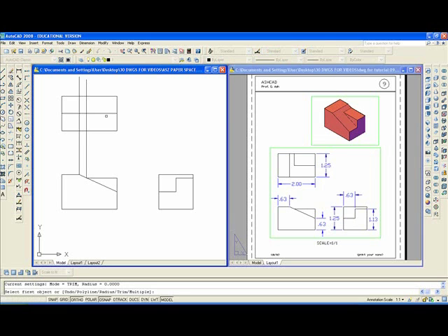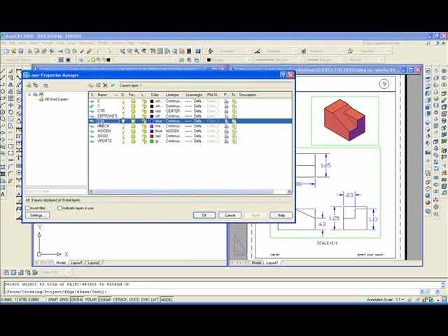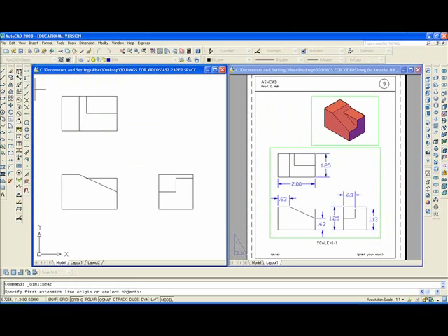F enter fillet. We'll clean up that intersection. Then we want to trim, TR enter, from that line and that, enter that. The three views are correct, so now we want to dimension, and so I'll click on layer, make DIM the current layer, and we'll start dimensioning from here up. Because the dim scale is 1, because this drawing will be plotted at 1:1.